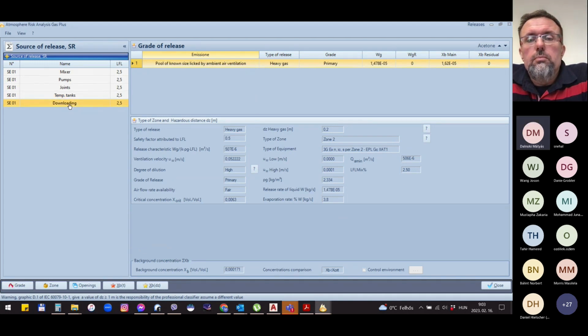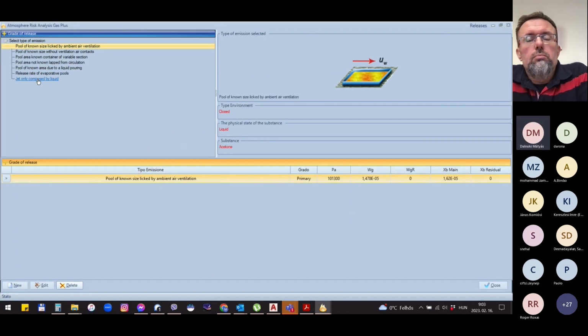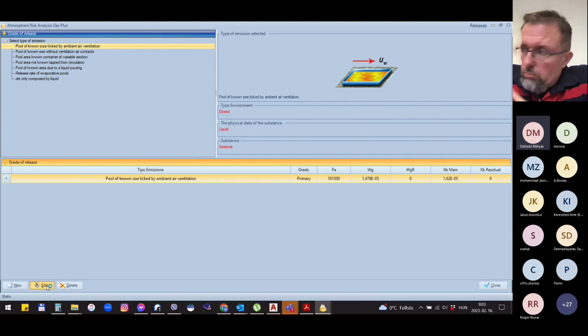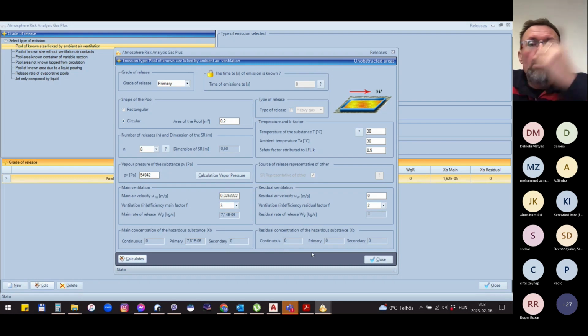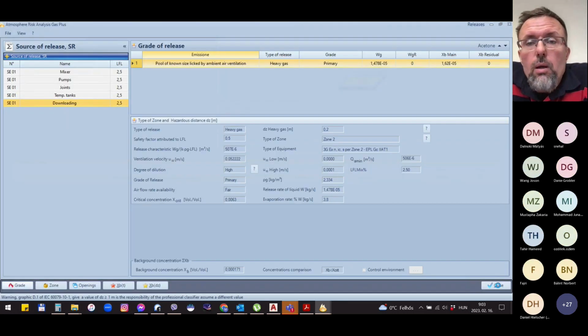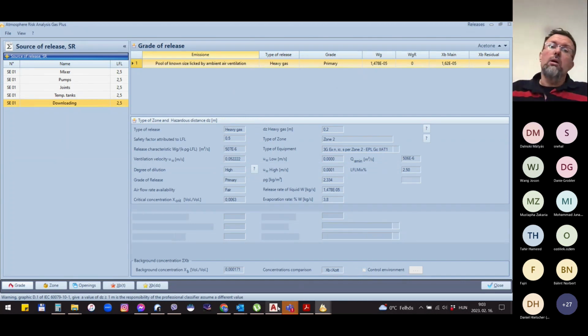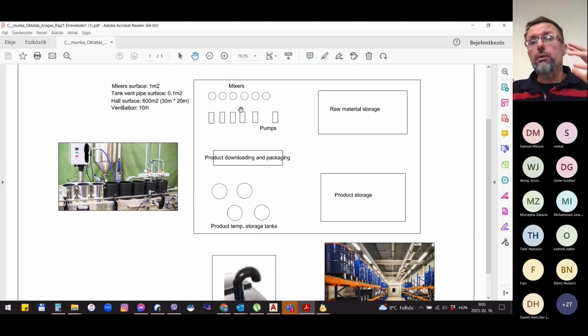As I see, with the 5 times air rate change, we are still good. So it means that we don't need to classify the whole room as hazardous area. In this case, we have to classify the equipment's near environment as hazardous. So in that case, in your drawing, you can make a 3D bubble around your equipment, and you don't need to classify the rest.